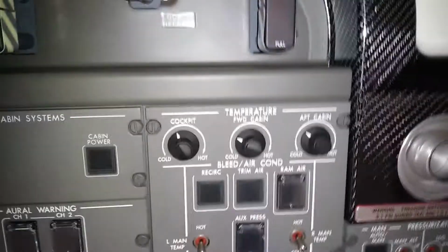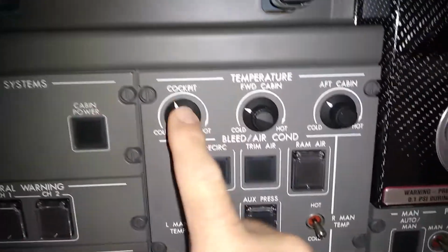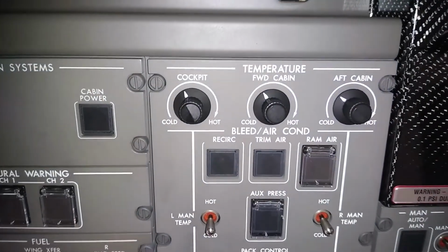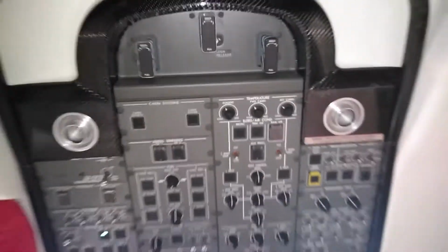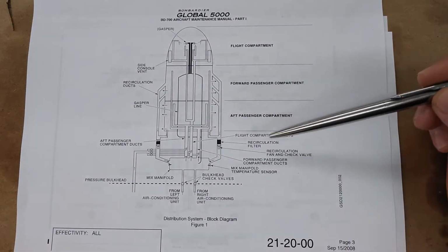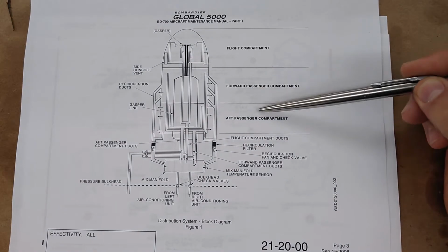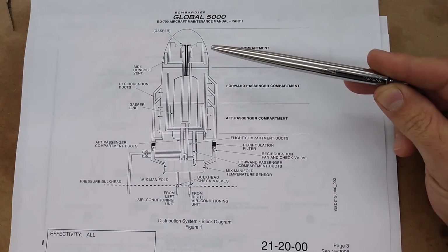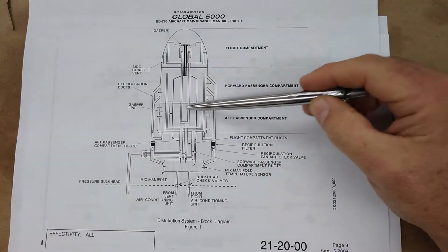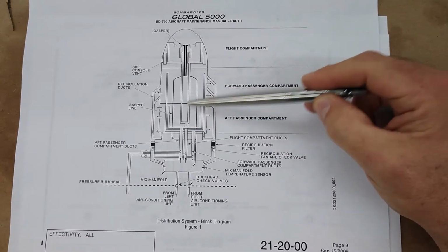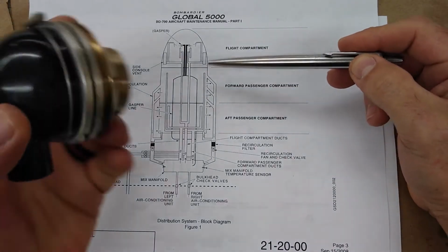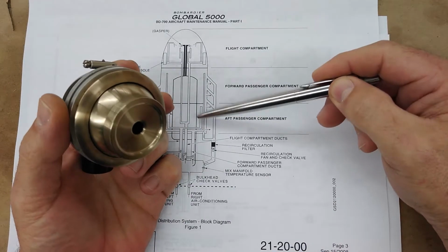And these are the 3 knobs where you control the temperature for each one of the zones through these knobs right here. So, after reading the temperature from each one of the zones, the controller in the cockpit can dial in with those knobs the temperature in the cabin in each one of those zones, in the cockpit and the 2 passenger compartments. Now, each individual Gasper, its job is for individual passenger comfort.